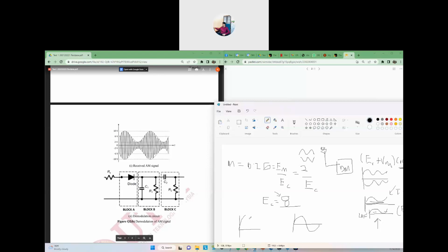Maybe for example, only as an analogy, we try to submit 10 volts, the one that we intend to transmit, the modulating signal before modulation, of course. But then when we do the demodulation, and it passes through the diode, the low pass filter, the DC blocker, then maybe we only have 0.1, for example.